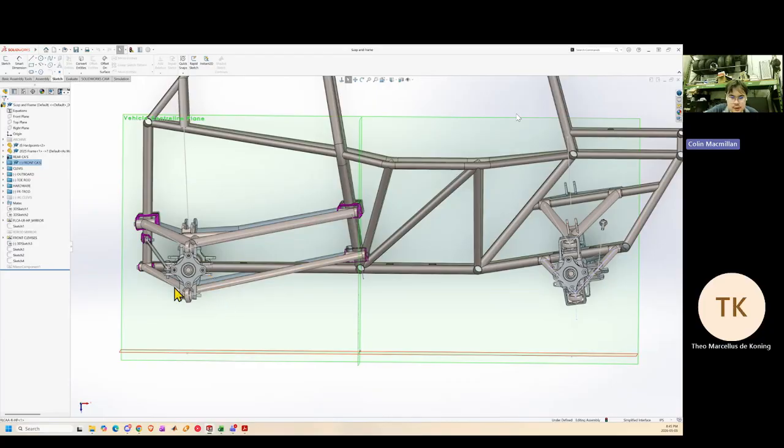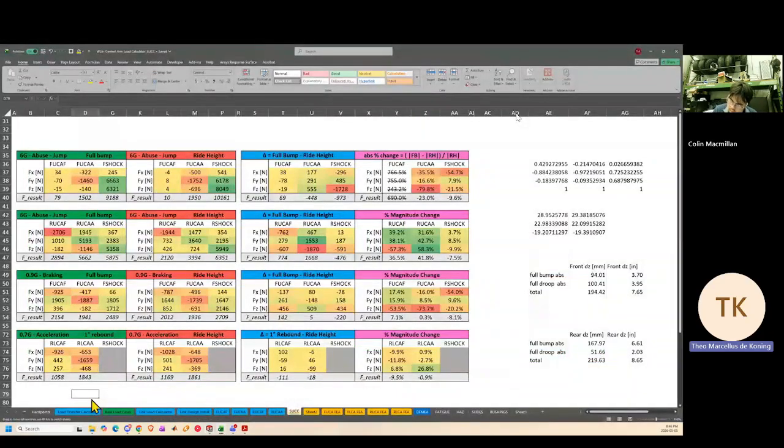And so you chose it to be rebound because when you accelerate, we have a little bit of anti-squat, which would basically raise the rear end. I didn't calculate how much anti-squat, so I just assumed it lifts the rear of the car by 1 inch. Okay, got it. Whereas the rest of these max out the shocks, which for braking is probably not true, but for 6G landing, it probably will be maxing them out.